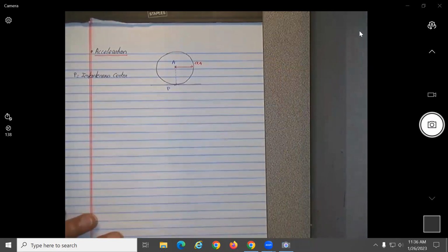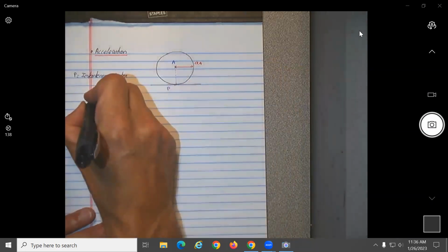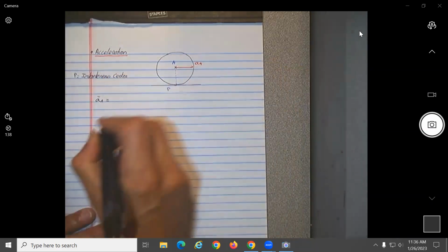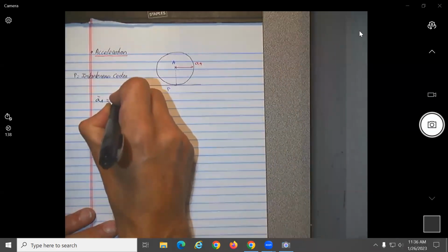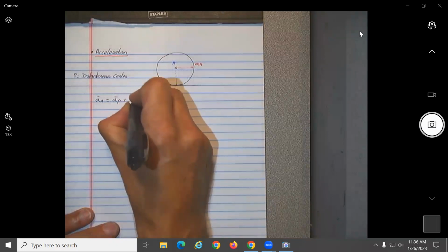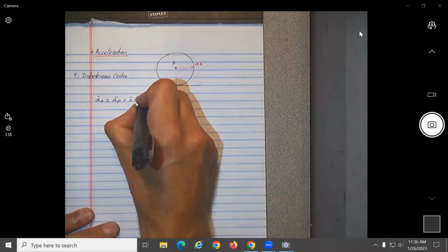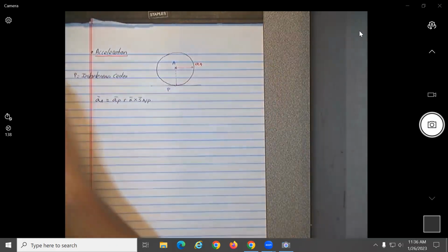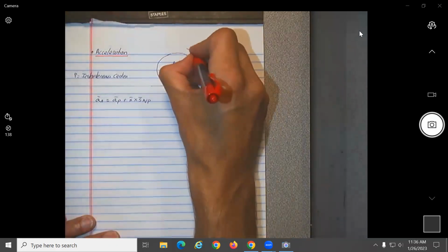Okay, so if we use the normal math and we say acceleration of point A from point P should be equal to what? A of P plus alpha cross S of A with respect to P. And let's say we want to put them in here. I didn't put them in the previous figure.